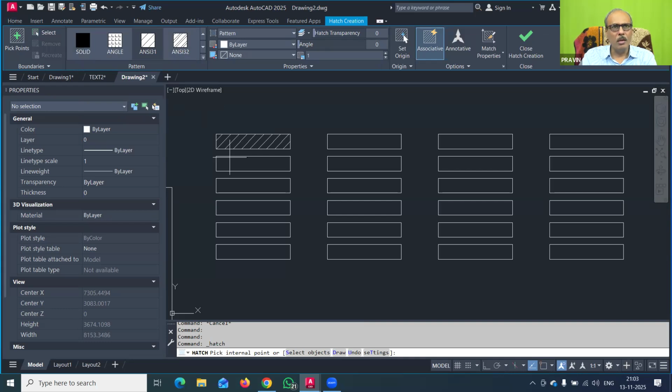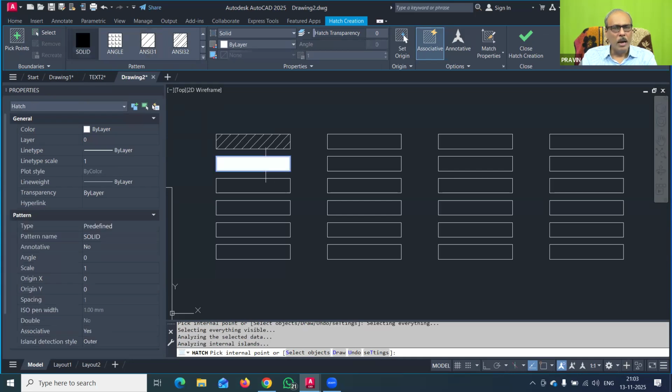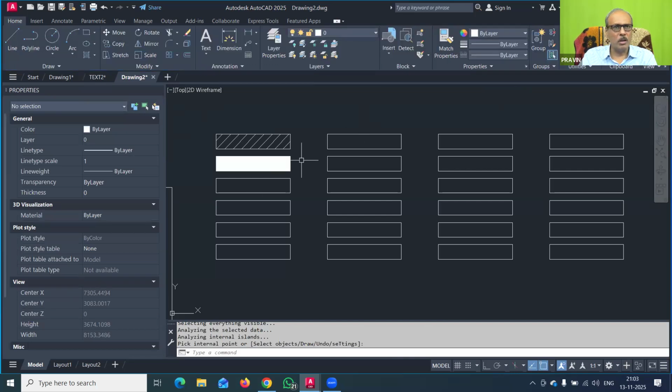Now suppose I want to fill complete color. So you have to choose the solid hatch pattern, click it here and close the title box, header. Yes, now this is the color pattern. This is just the plain color you want to make in the printing. This is required sometimes to give a color to the various blocks. So how can that be done?